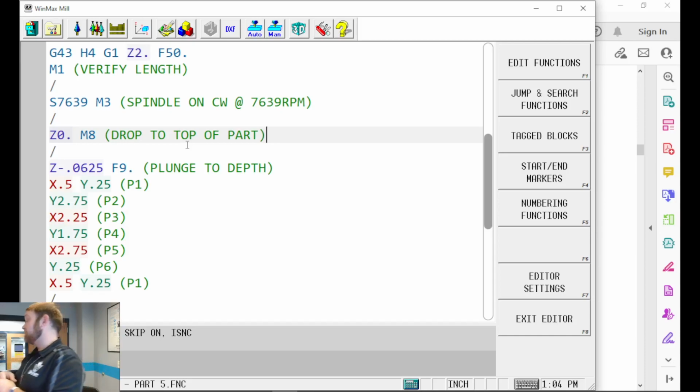You get away with it a couple times in aluminum, plastics, things like that, because they're soft metals that aren't very aggressive. When you're cutting different types of steel, especially tool steels, alloy steels, pre-hard steels, a straight plunge is just a big no-no. You're going to work harden that material, and you're going to end up losing your end mill, and then the piece of material is probably not going to be any good either, because you got to work that out of it.